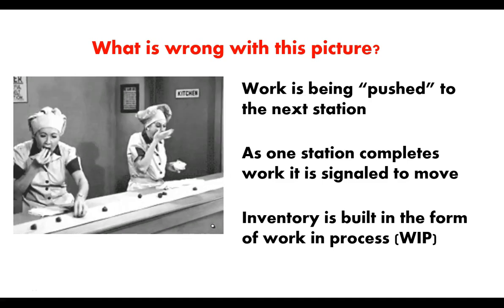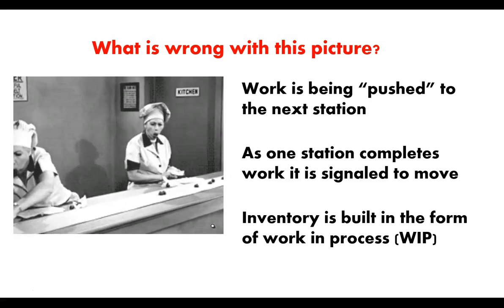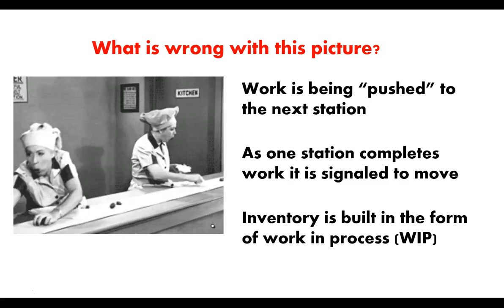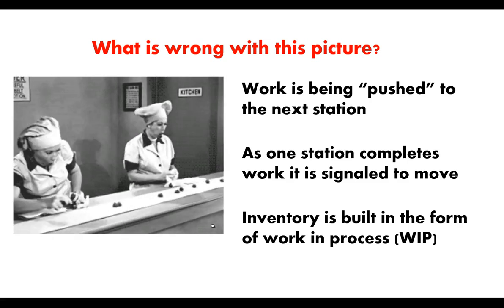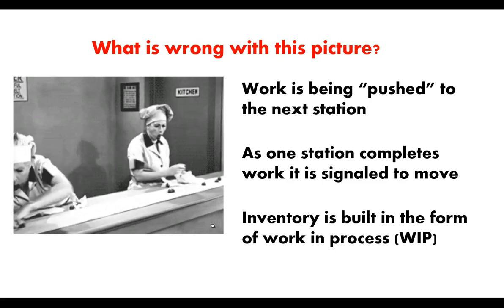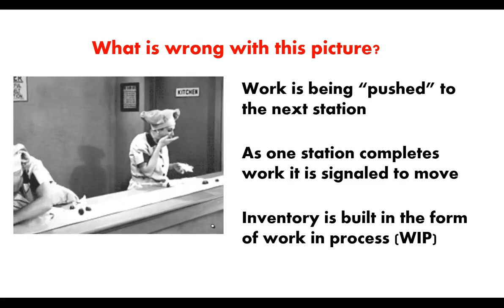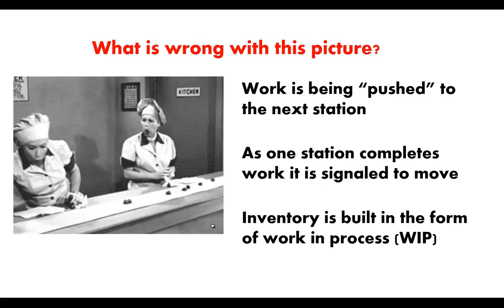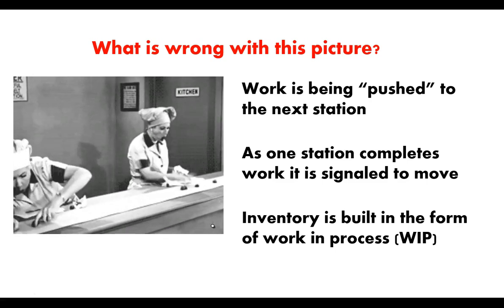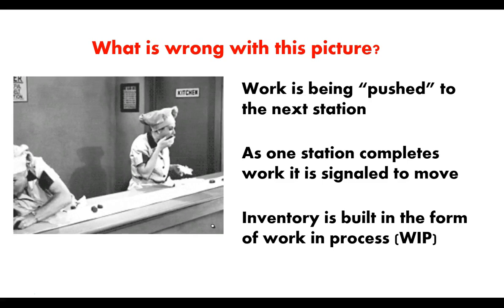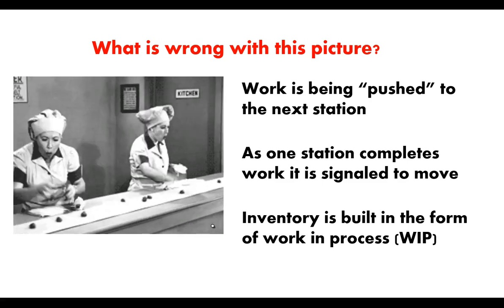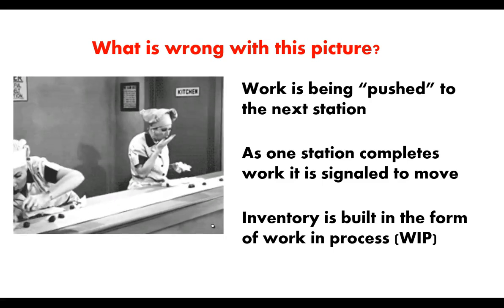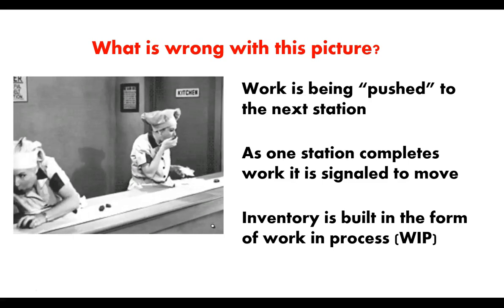This is another form of inventory. It's the work just sitting on the floor, a work in process, which is still a form of waste. One of the many forms of waste that we've looked at here. So again, when we think of the 7 forms of muda, and this is going to be an ongoing theme in this particular module 4, these different systems, these different tools that we're looking at, will a lot of times address very specific forms of muda. And what we're going to be thinking about in this particular module, I still haven't said what the official title or official name of this is, actually deals with very specific types of muda. Motion, inventory, rework, and work in process.